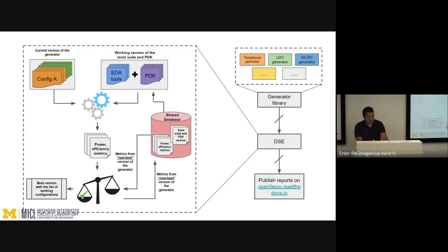We plan to use the same approach for the technology design loop and modeling, which require improved models. So basically, we create the structures, but we want to make sure in a CI, when we do measurements, we compare different tools. We have Xyce and ngspice. We get different results from these tools. Which one is closer to silicon results? These are very important questions, and we need to get an answer to that. And the open source community or initiative actually helps us define these things and move forward.